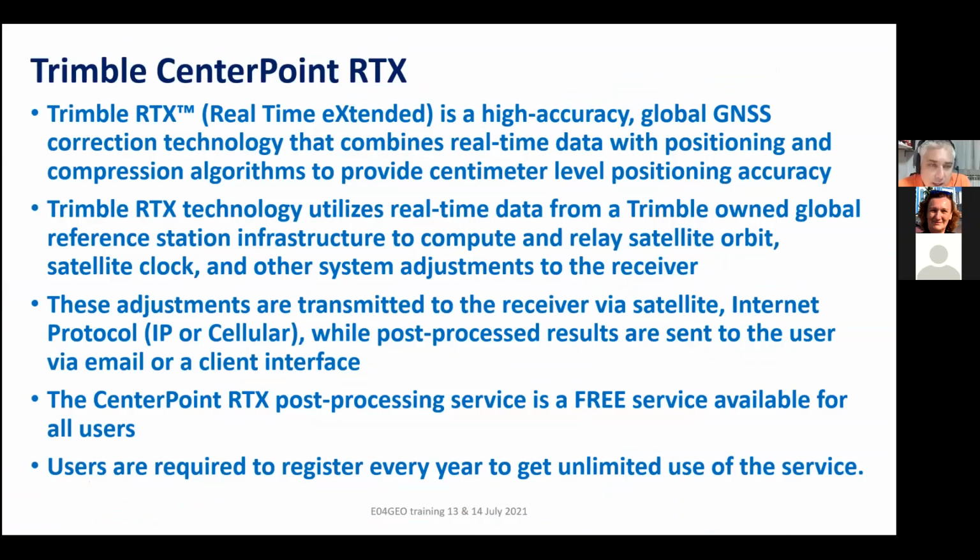So Trimble RTX is an acronym of Real-Time eXtended, a high accuracy global GNSS correction technology that combines real-time data with positioning and compression algorithms to provide centimeter level positioning accuracy.